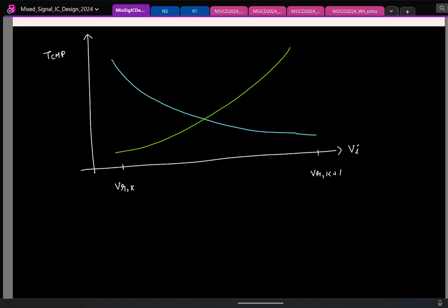And exactly at the middle reference voltage, the delays will be equal. That's what we exploited, right? This was giving you a 2x interpolation. Here we just checked if the time taken by the top comparator versus the bottom comparator is greater than 0 or less than 0.